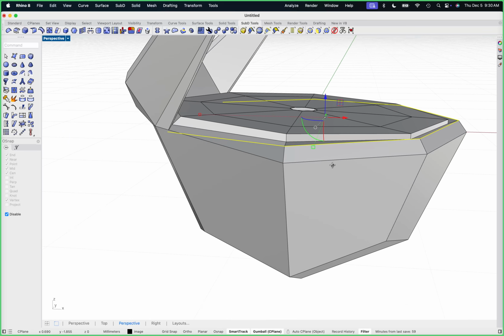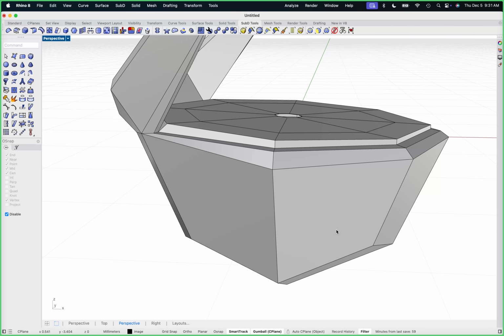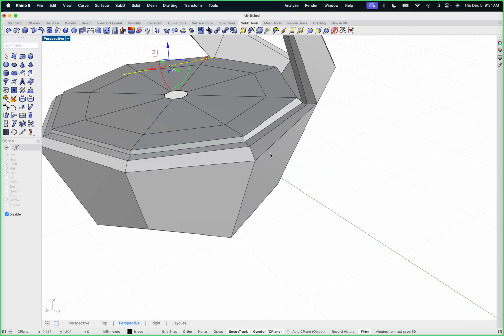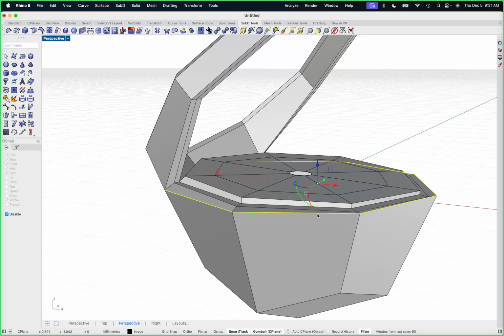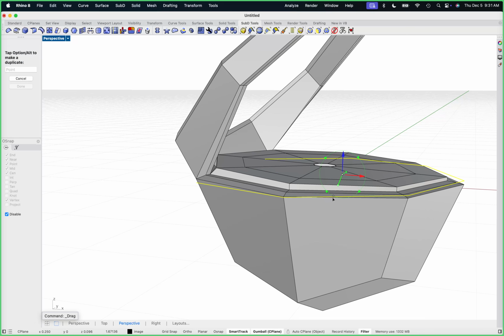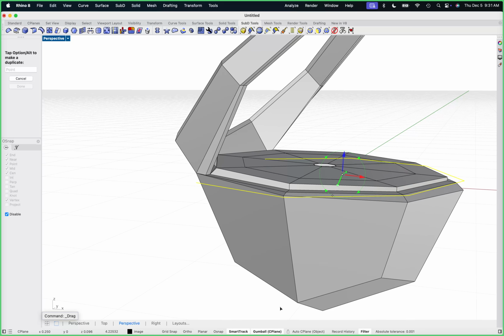That scale to 0 is really, really useful in SubD because it allows you to reset things, so that things that may have gotten a little squirrely on you, you can bring back to order. I'm going to do the same thing here. And then I'm going to just rotate that a little bit. One thing to notice, the farther I get away from the gumball while I'm holding down and moving my cursor away, I get finer control. So I can actually slow down the action of that gumball.